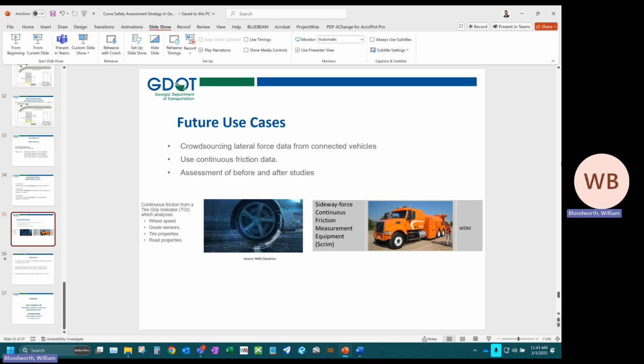So you can use your traffic signal to do different things when a train is coming versus when the circuit or the preemption is not operating correctly. That's on the train equipment side. On the traffic signal side, it's just limited to what you can do in your controller. Anything that you can do to monitor the health of your signals and the traffic cabinet, you can do to help monitor the health of your preemption equipment inside your cabinet.